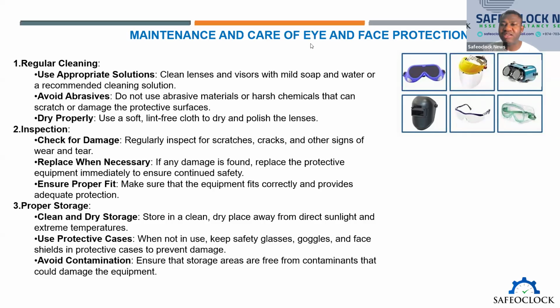So you should inspect your safety glasses, even the face shield, regularly. Inspect for scratches, for cracks, or any other signs of wear and tear. When necessary, it should be replaced when it's damaged. It should be replaced when it's no longer giving the protection that you desire.